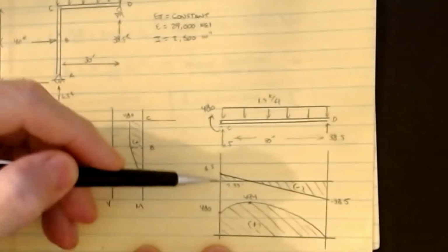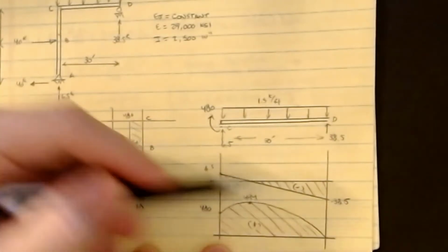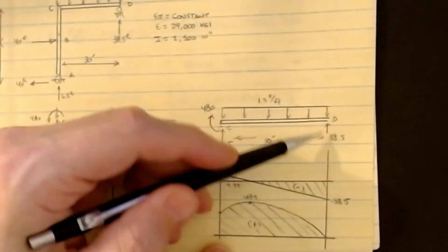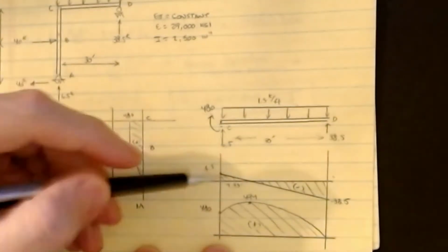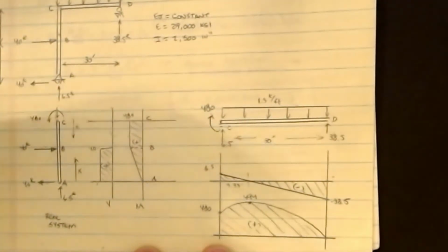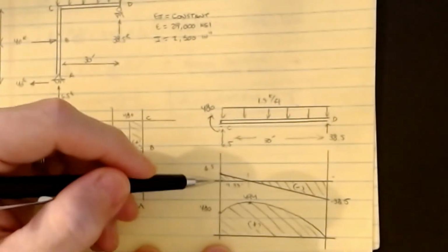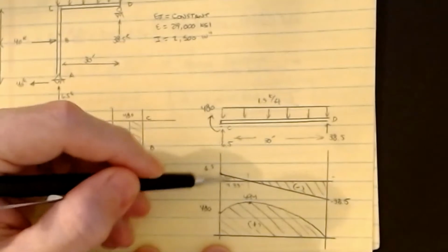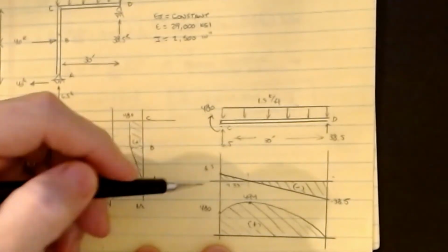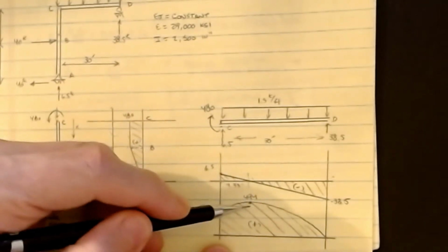Okay, so if I go through and draw my shear diagram, we know that it's linear. So it goes up to 6.5 and it's linear down to minus 38.5, and then that reaction brings me back to 0. We know that it crosses 0 at this point, and you can use proportions to find that. But again, I'm going to assume that we know that value because I want to get into the methodology. That distance ends up being 7.33 feet from the left end to where the 0 is. And that point is important because that's the maximum moment.